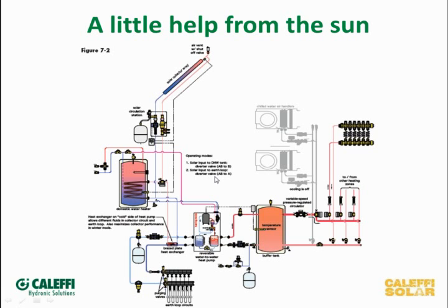Now, I did see a system like that recently last week when I was up in Fairbanks at Weller School. That's exactly what they've done up there, they put in a system. I think they've got about 8 collectors on the side of the building, and they're just using that to dump into the loop field. In fact, for some reason, they're not even doing a domestic water load. What they're doing is they're going to run it this year without the solar input and get some baseline information to see how that system performs on just the heat pump for the school. And then they'll bring on the solar next year, so that they data log that system, and they'll be able to tell how much the solar is actually going to do to it.